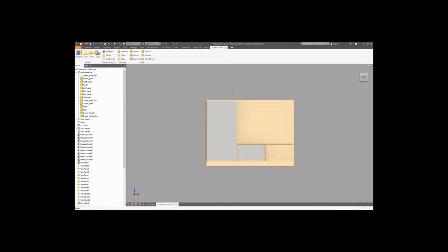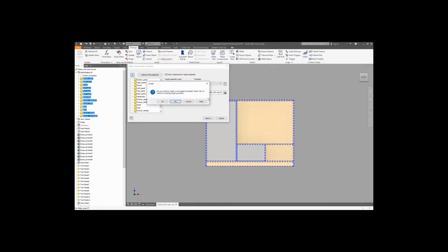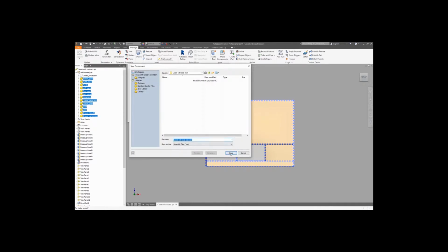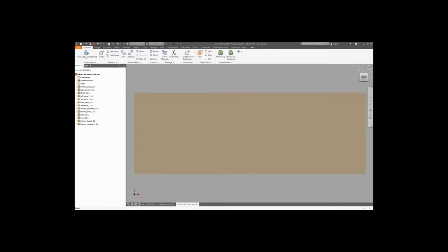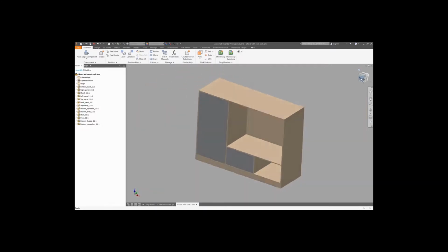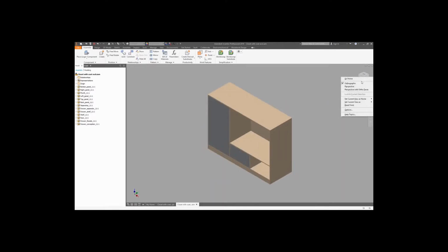When the construction design was finished, you need to design an assembly, utilizing the solid bodies as a source for making the parts. So select the solid bodies and use Manage, Make Components in order to make the parts. So now we are on assembly level, and we can define the front on the view group. As well, you can define the home view using right-click and choose Fit, the same as you did in the part. Now save the file.